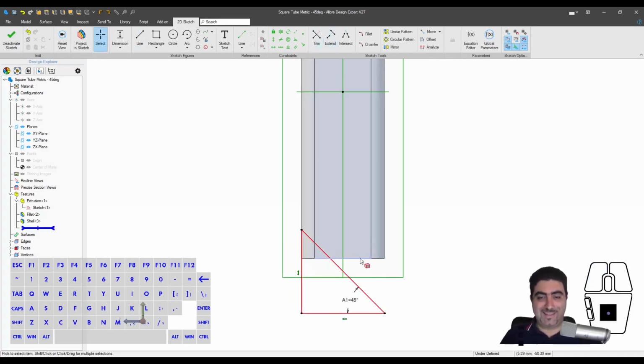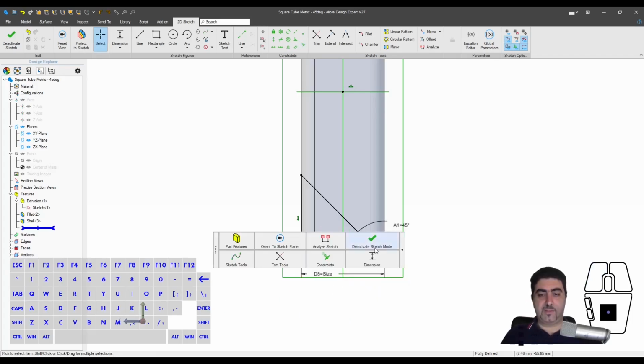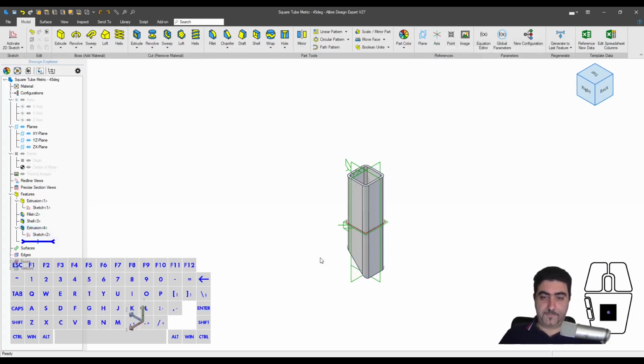And this is going to be size, and I'm going to use the midpoint constraint with 3 points. Put this in line with the rest of the tube and attach that there, and bring up the hold bar, extrude, cut, shift, tab, down arrow, through all.